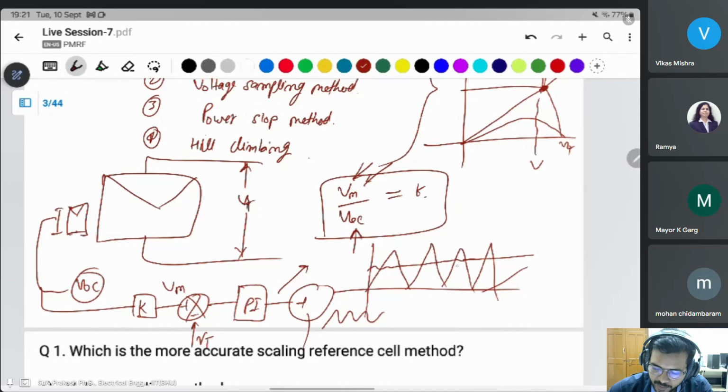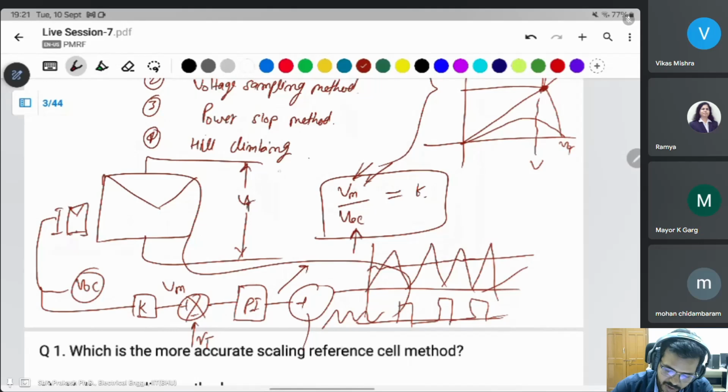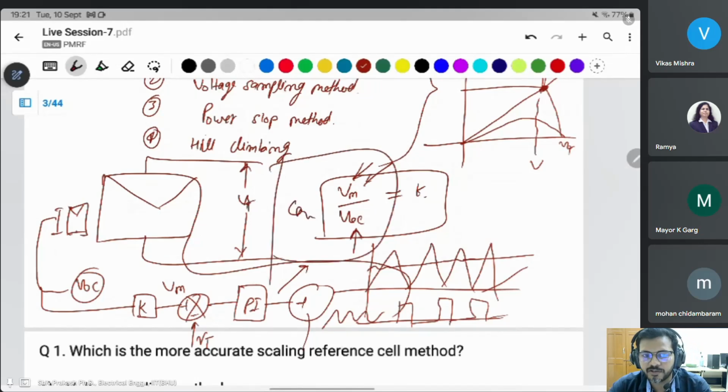This will be the on-off time period given, where it is on and off. This duty cycle is directly given to the converter, and the converter will track the maximum power. Because of the PI controller, you reduce the error between VM and VT, to make VT equal to VM. Same thing in the current controller.